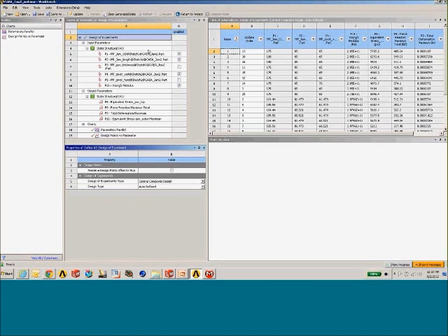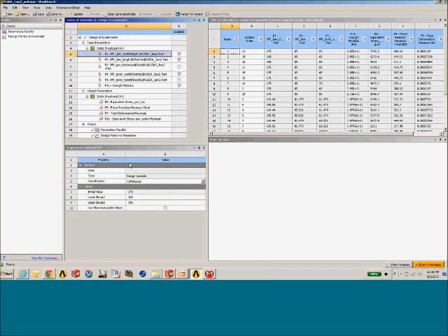We go next to our input quantities, and we eliminate the input parameters that we saw had weak correlation. And then we specify the lower and upper bounds of our parameters, and then the type of parameter that this is going to be defined as. It could be continuous, so it's going to be an upper-lower bound within that range, or it could be something like a discrete parameter, where this particular parameter can only take discrete number values in that process. So it all depends on how that parameter affects the overall design.